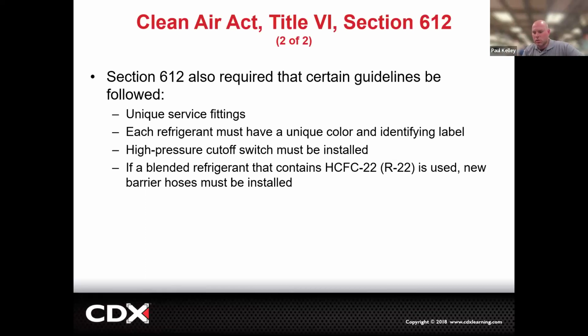So if you were to just use the old school R12 hose but put in the retrofit to R134A, the R134A is going to have more of a tendency to leak. That's why, to do a proper retrofit, we should really change the hoses to barrier hoses. You should have it reworked. However, you could do a retrofit and just run the hoses. Just know it's going to lose refrigerant over time. How fast? Tough to say. If it lasts a couple years, you could at least get a couple years and then have to recharge it every couple years. Cool.